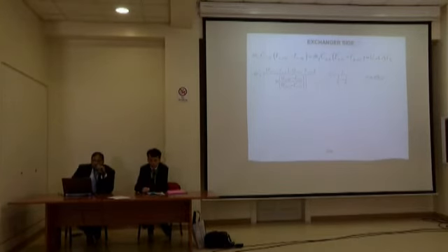If we look at the flow corresponding to an outer to inner diameter of 1.75, the Reynolds number is almost below 2300, which corresponds to the transition from laminar to turbulent. This is why the heat rate for the case of 1.75 is almost constant. As we see at 0.36 and 0.4 kilogram per second, the water flow is transferred from laminar to turbulent. This is why sudden changes occur at 0.36 and 0.4 kilogram per second.